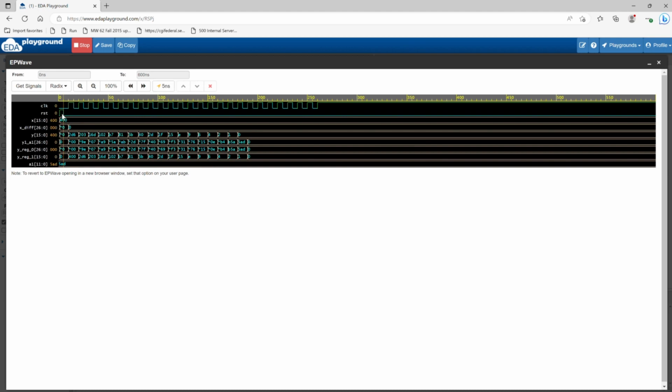As you can see here, our output starts at hex 400, which is 1024 in decimal, and slowly decays down to 0. Here we can see our bus widths are indeed different. Now they are 16 bits wide. The coefficient, which used to be 16 bits in the previous version, is now 12 bits wide. Now we will move on to our third example, where I will change the specifications completely to reword and reformat the language used and show you that the results generated will still be as good as the current one.